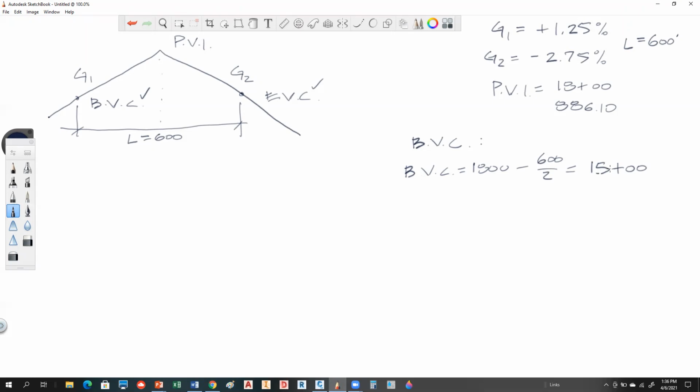Okay. One thing you'll notice also with horizontal curves, the PCs and the PTs are going to always start at really strange stations because there's no way to make things real equal and even. With vertical curves, we very often will force the PVI at a nice even station, and so therefore these guys are going to be usually nice stations. Okay. If a designer is not doing that, they're not a very good designer. They just make it harder for people in the field if they don't do it that way.